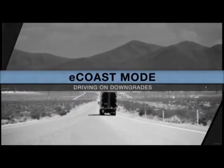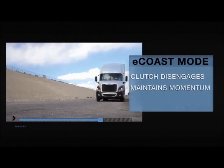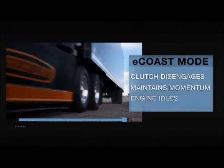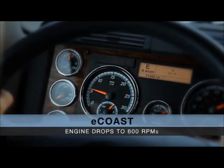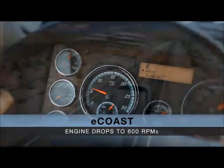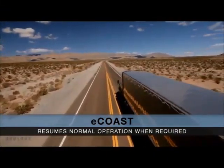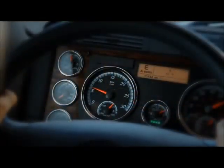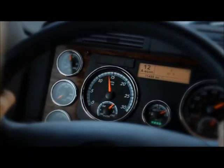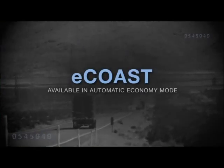When driving on downgrades, the DT12 may enter E-Coast mode. Here, the transmission temporarily disengages the clutch, so the vehicle maintains momentum while the engine efficiently idles. Engine RPMs will drop to 600 and an E will be visible in the gear display window. E-Coast will remain active until the electronics require torque or there is any input from the driver. At that time, the DT12 will safely and seamlessly resume normal operation when required. E-Coast is only available in automatic economy driving mode.